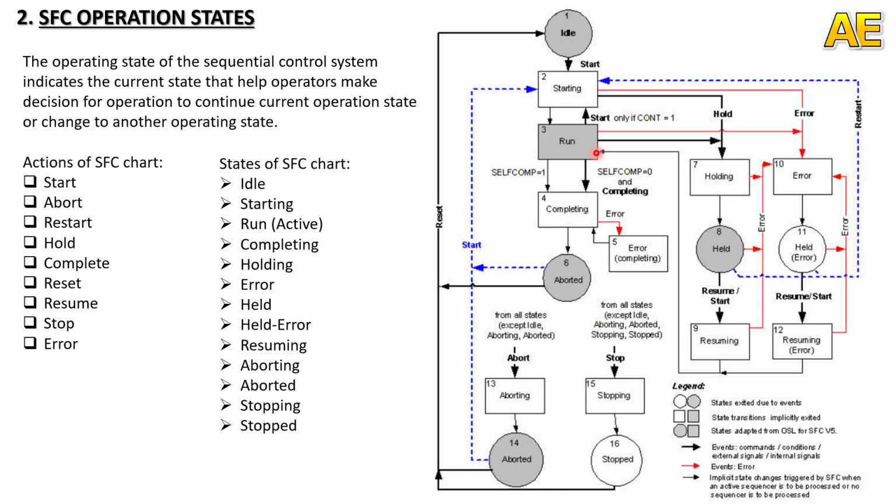In case of hold for another reason, for example hold for maintenance or lack of material, the flow is the same as with error, but we go this way, hold, and change to the state holding and held. And then resume, start resume, and come back to run.